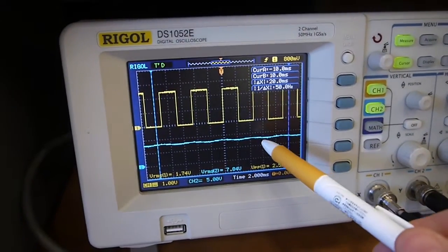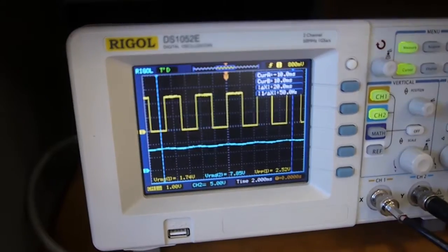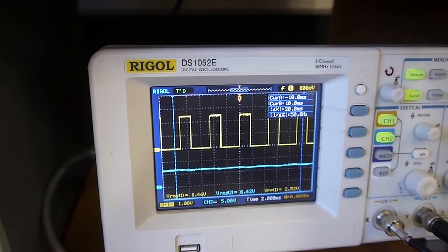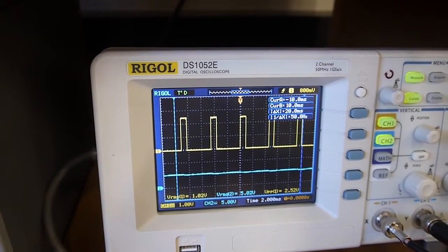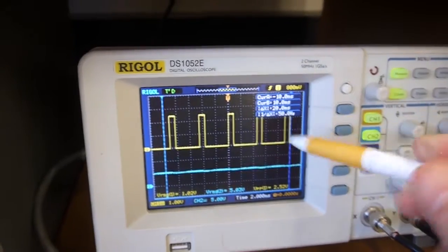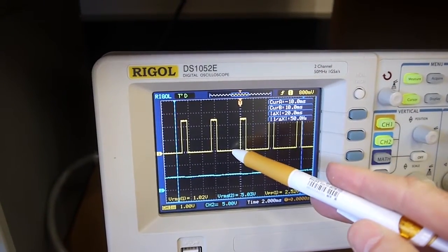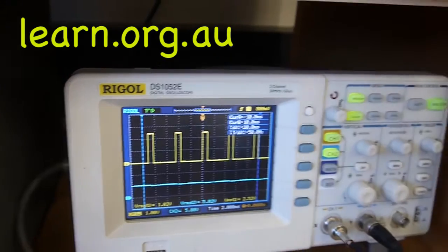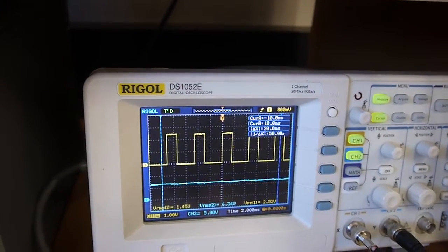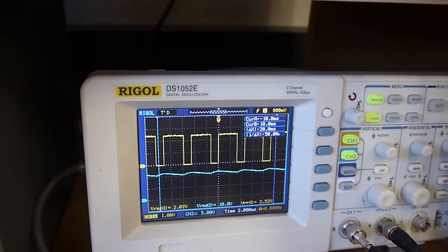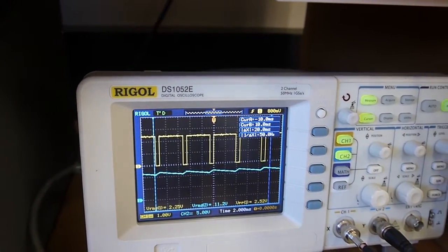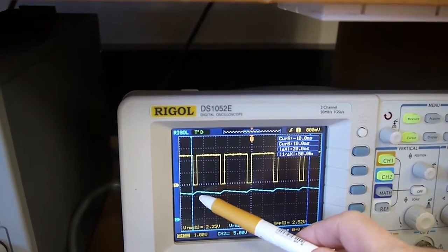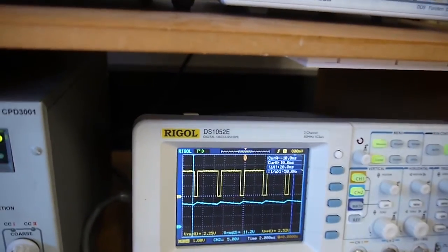But if we change the duty cycle, look what happens to the DC output voltage. I'll go ahead and change that duty cycle now, and that's making the duty cycle smaller. We've actually got less on time and more off time, and the voltage fell back towards 5 volts DC. But if we go in the opposite direction and we make the duty cycle higher, we can dramatically increase the output, and we've now increased the output from, well, 5, 10, it seems to be about 12 volts DC.